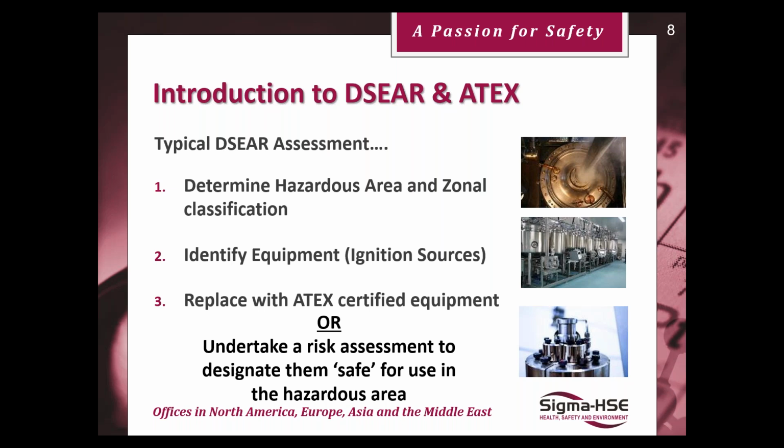This is the hazardous area, which is the zonal classification. For example, you have a natural gas pipeline. You find out that at the flanges or the pipework fittings, it could leak. It could form a hazardous area. This is the bubble, how big it is. Is it a 1 meter distance, half a meter? That is your flammable atmosphere.